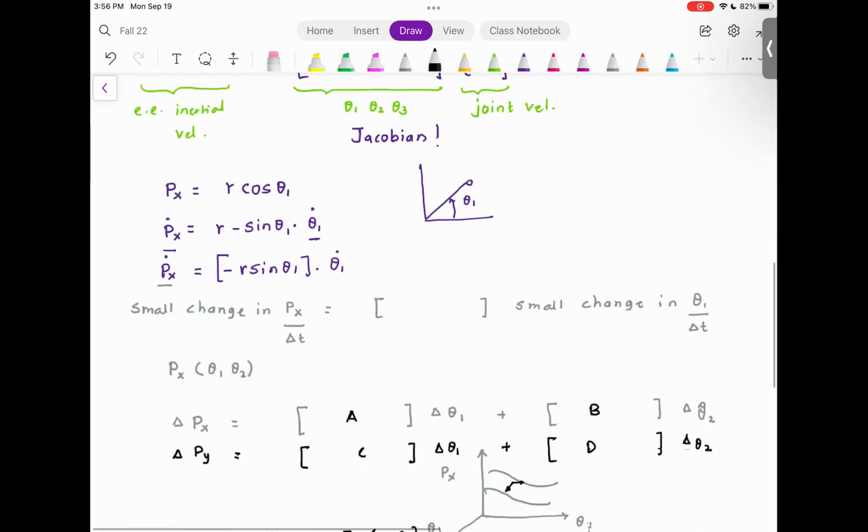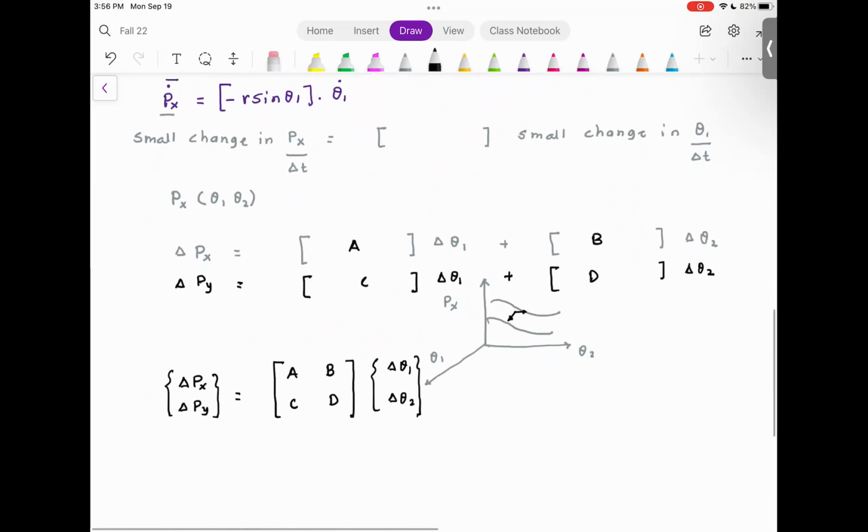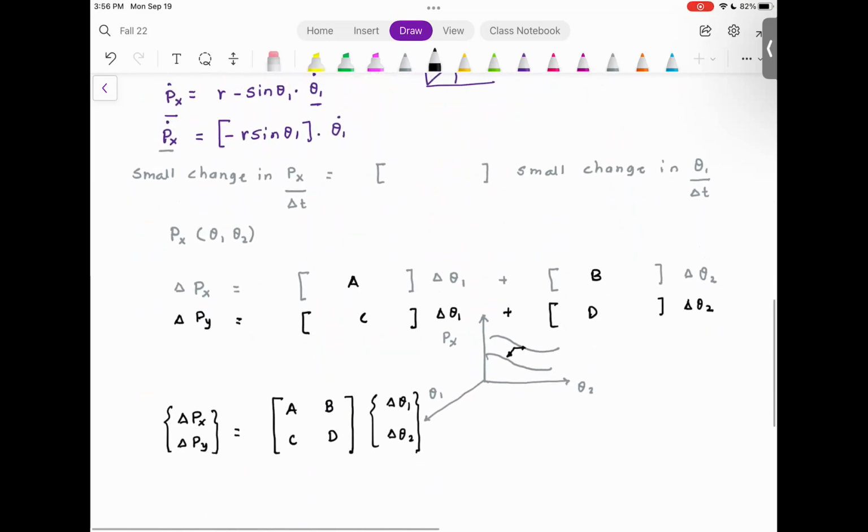So all this information is very, very important. And yeah. So you said those equations are true when the angles are close to 0. Very, very small. So you mean theta 1, theta 2, theta 3 should be close to 0. At each snapshot, if you are sampling the joint angle variation at 1000 hertz, then basically those joint variations are going to be very, very small. That's why the linearity assumption is applicable. Otherwise, the linearity assumption is not applicable.